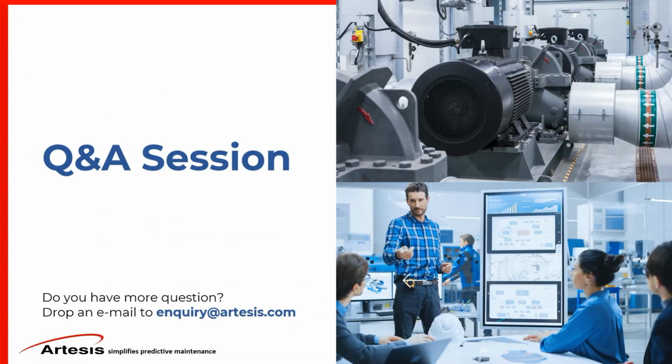So we can do that. But this will require a manual spectrum analysis. It's not going to be automatically analyzed, but the system will generate a transmission or driven equipment, in this case, the pump. So you will have to follow up with spectrum analysis to calculate the impeller or vane pass frequency for that impeller on a multi-stage pump. So it's a more advanced analysis, but it can be done.